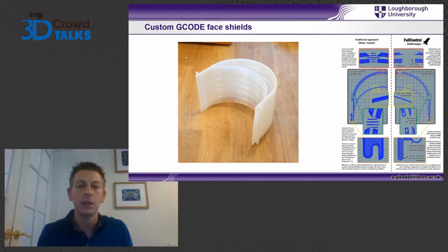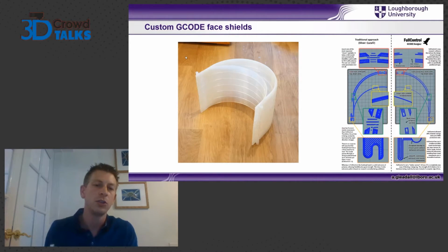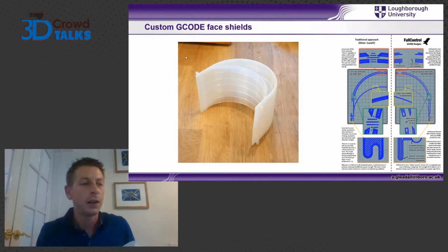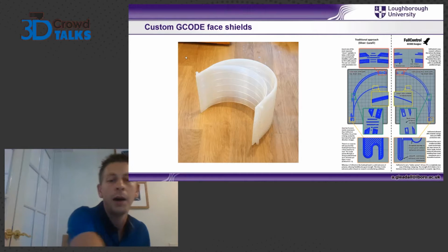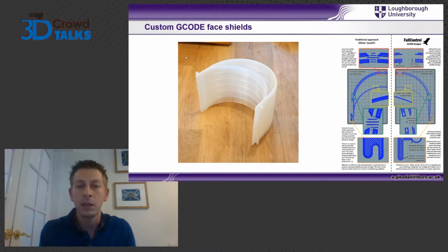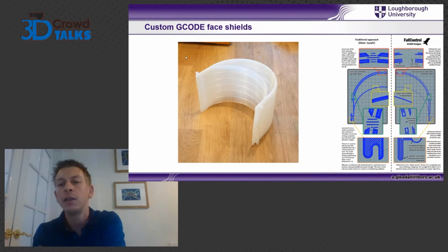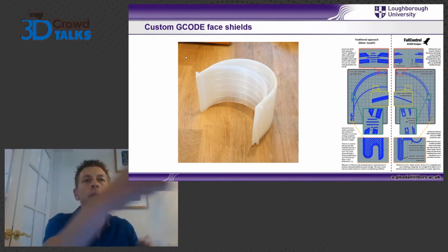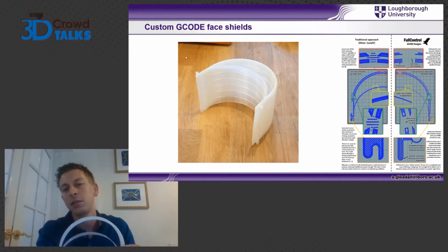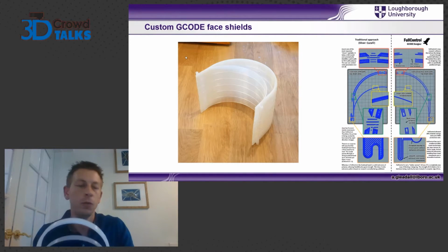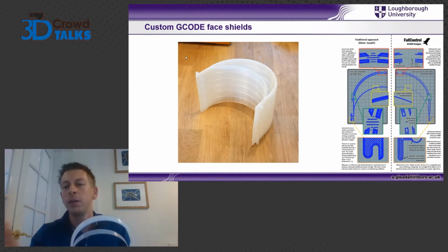And when there's too many things to try and fix, we can reduce stringing by printing slower. But I could see it was just unnecessary. So we defined the whole toolpath for this part, and then printed it in a really quick way, because it was properly optimized for printing with 3D printers. So you can see on the right hand side there's a little screenshot showing a top down view of the sliced visor on the left, and then the one produced with custom G-code on the right.